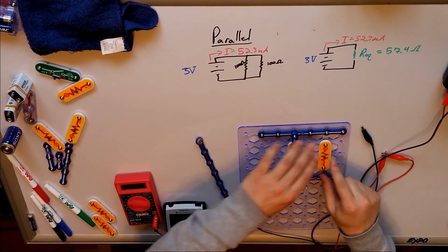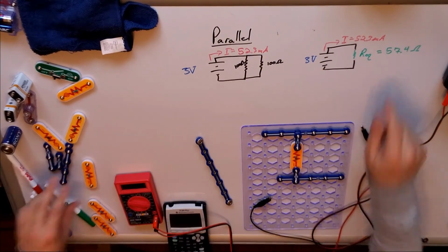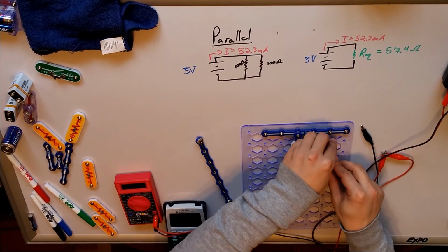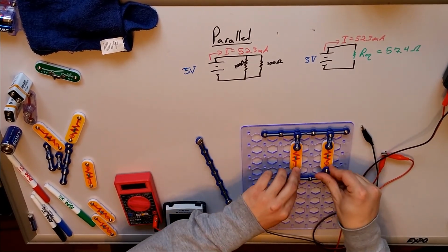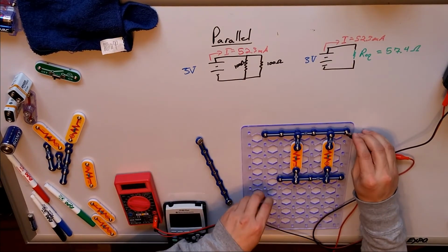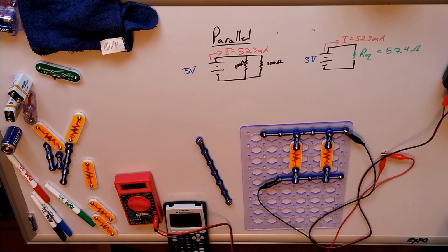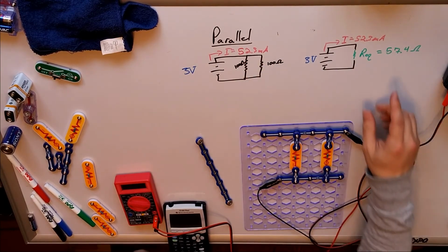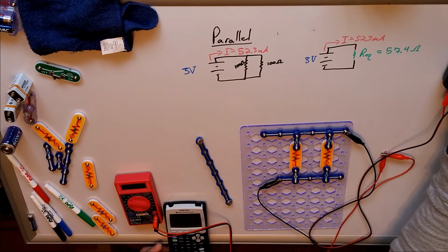Because again, it's nice starting off with the two same numbers, because then we can kind of see a relationship with the number that comes out, but it can make it hard to identify exactly what's happening here. Because parallel's a little bit trickier in how we can actually calculate that. With series, we just add them together, but clearly that's not what we're doing here, because we ended up with a smaller resistance. One resistor replacing these two is somehow even less than the two of them. Good to note.